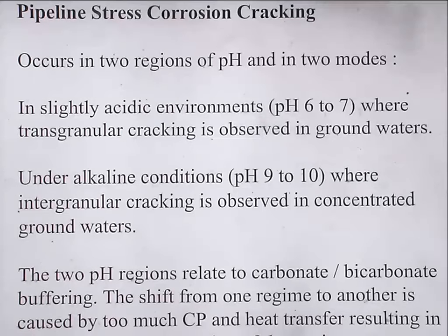On the weld, this is the darkened area, and that's purely because of the weld ripple. This is the more normal crack front. You get a curved crack front. But it's the same thing. The sides of the crack are passivated, and the tip is the only bit that stays active and corrodes.